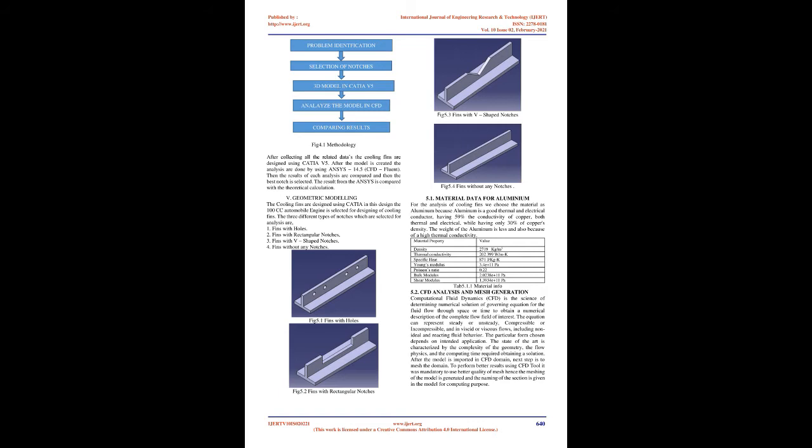Vivek Kumar, Dr. V. N. Bhatt Arya, Ref. 4, CFD analysis of an elliptical pin fin heat sink using ANSYS Fluent v12.1. The present study carries out numerical physical insight into the flow and heat transfer characteristics. The governing equations are solved by adopting a control volume-based finite difference method with a power law scheme on an orthogonal non-uniform staggered grid.